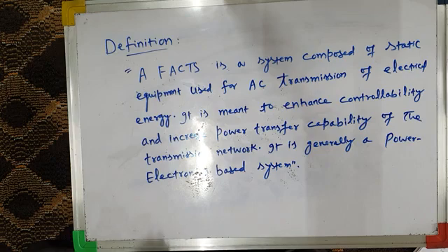I mean, you can control the flow of active power, and you can make the compensation of reactive power. You can control the flow of active power through parallel or interconnected power transmission networks. That is the beauty of a FACTS controller. So it enhances the controllability of the power transmission network, and we can also increase the power handling or power transfer capability of the existing transmission network.